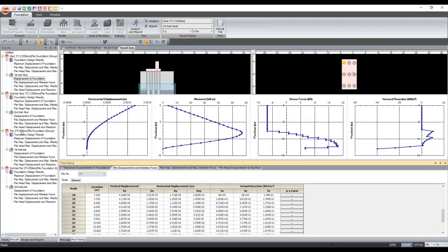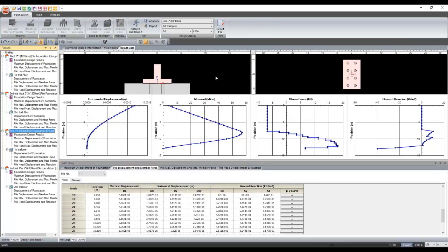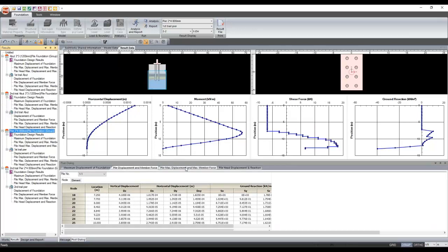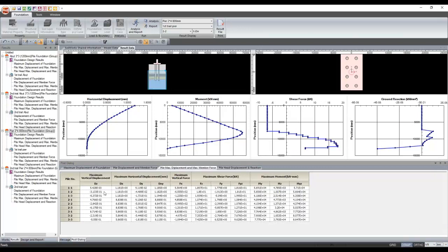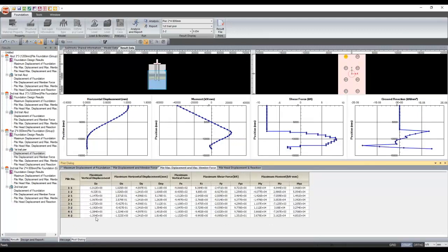Underneath the piers, we got 2x4 piles. So here you can see this is your 2x4, this is your pile cap, this is your pier, and here we got piles. In the piles, we can find the maximum displacement is very low. It's around 0.05 mm in one pile, and it reaches around 0.5 mm in the 3-3 pile. So this is the maximum displacement which you are finding.